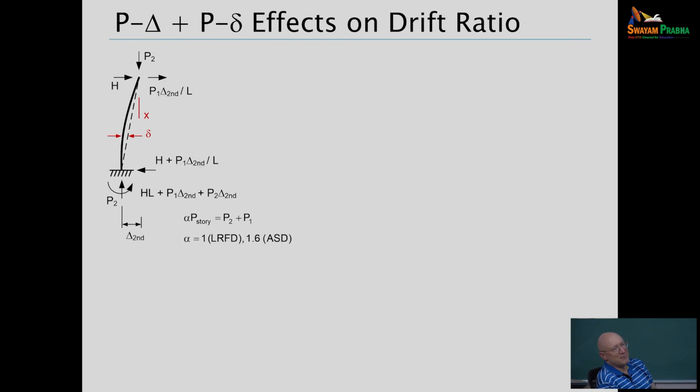If there's no axial load, there's also no P small delta because there's no P. The chord is between the deflected member ends, and because we have bending in the cantilever, the reference axis of the cantilever is offset from the chord at different positions along the length. If it's just a horizontal load, then it's a sway problem. If there's no P, there's no P small delta, correct?